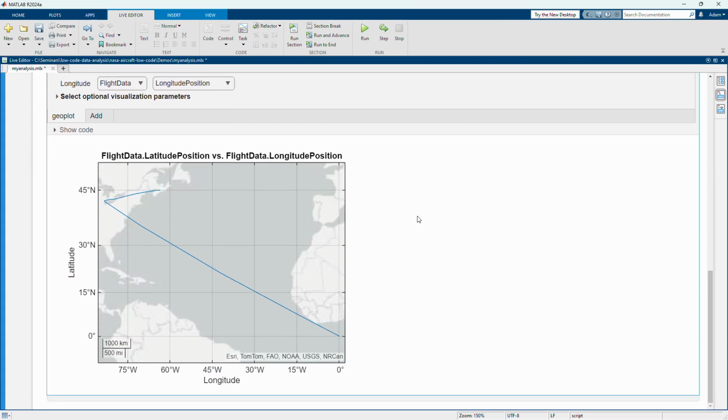Okay, and that looks a lot better. So now we can see the flight path from Halifax to Detroit, like NASA said. But we can again see a different kind of anomaly here, where at the very end of the flight, the GPS coordinates briefly go to 0, 0. So this is kind of similar to what happened with the oil pressure, where at the very end of this flight, whatever kind of sensor is tracking latitude and longitude just output some kind of default value very briefly before it was turned off. So this is another anomaly we're going to need to clean up.